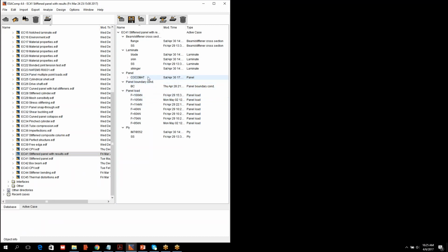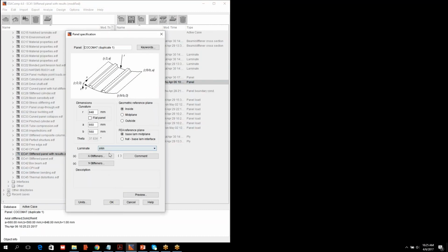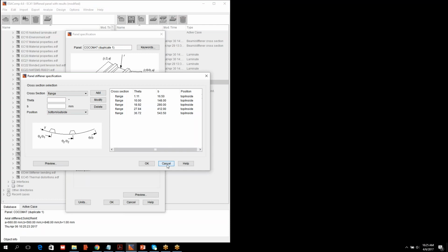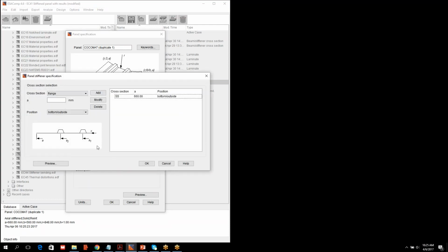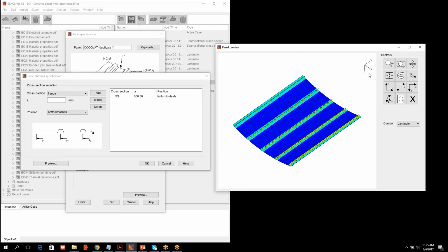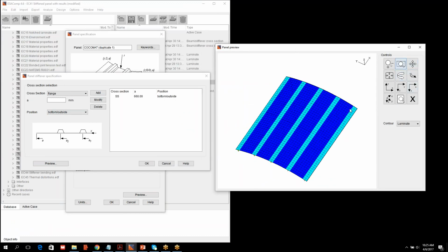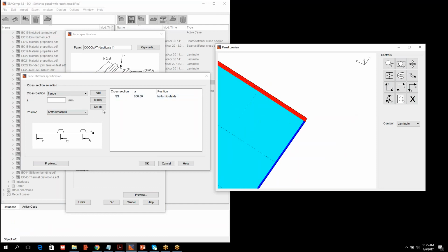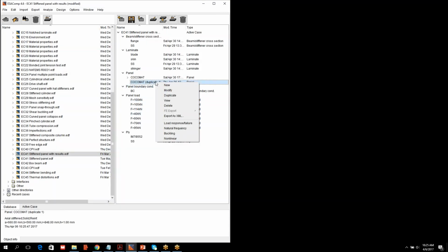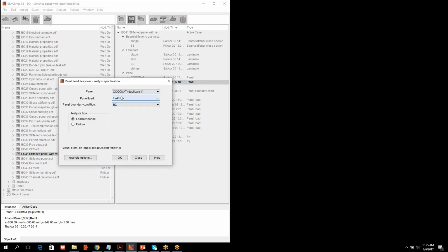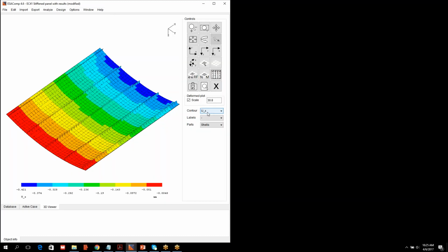One more thing related to this example: if I take a copy of this panel and remove, not the axial stiffeners, but the transverse stiffener, so this stiffener is now removed, and I make a linear static analysis with the lowest load level, and I look at the end shortening, one can see that it's not uniform because there is no transverse stiffener.